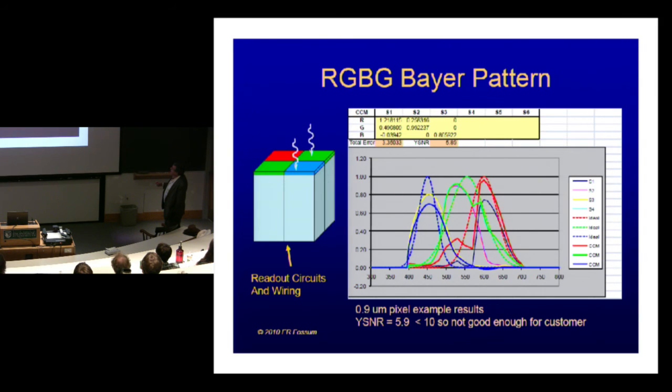This is the blue signal as it comes out raw. Ideally, we'd like it to look like this dash curve. And after we apply the color correction matrix to these signals, we get something that maybe is this fatter blue curve. Not quite perfect, not quite ideal, but better than what we started with. Same with the green and the red. We wind up with some negative coefficients and some other things going on, and not much light getting in.